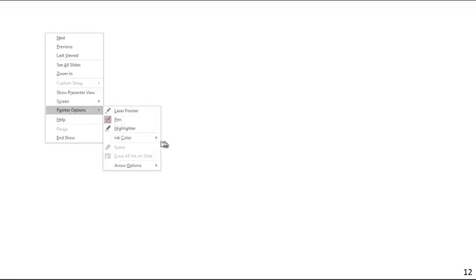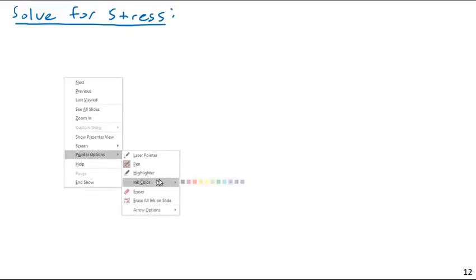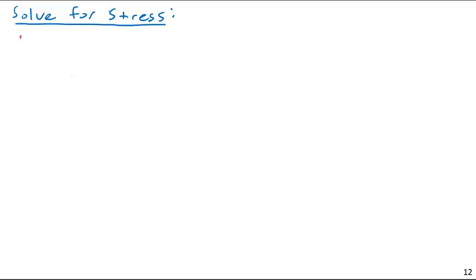So we have our two torques, and now I'm going to solve for the maximum stresses. Once we have the torques, the stresses are fairly straightforward. Tau AB max, the maximum stress along section AB, is going to be equal to the torsion in AB, TAB, times rho max over JE.